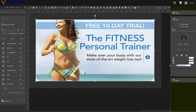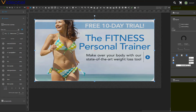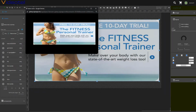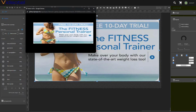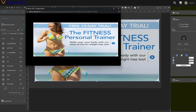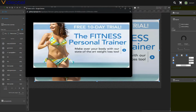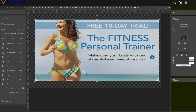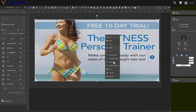Let's go ahead and modify this to be, let's say, 85 and 30, so you can see the difference. Go ahead and preview the presentation one more time. Notice that if I run the presentation in different screen resolutions, it's still maintaining the proper position of the image and respecting the properties that I've set right here. So taking advantage of auto-scaling and anchors will allow you to build a presentation and a scene that maintain its ratio regardless of what type of screen resolution you're going to run it on.